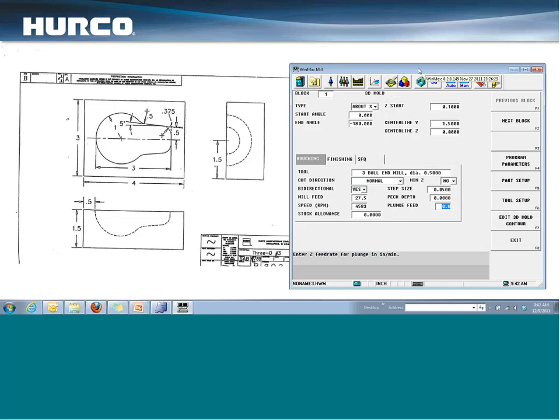So that's basically how 3D mold works. You see the process there. You define a contour. You then tell it how you want to transform that contour, either translating along an axis or rotating around an axis. And of course, you've got the parameters down here to fine-tune the way that's going to cut. This minimum Z that we have here, I have a slide a little bit later on when we're talking about swept surface that'll help explain that. So we can forget about that for now, and I'll clear that up a little bit later.